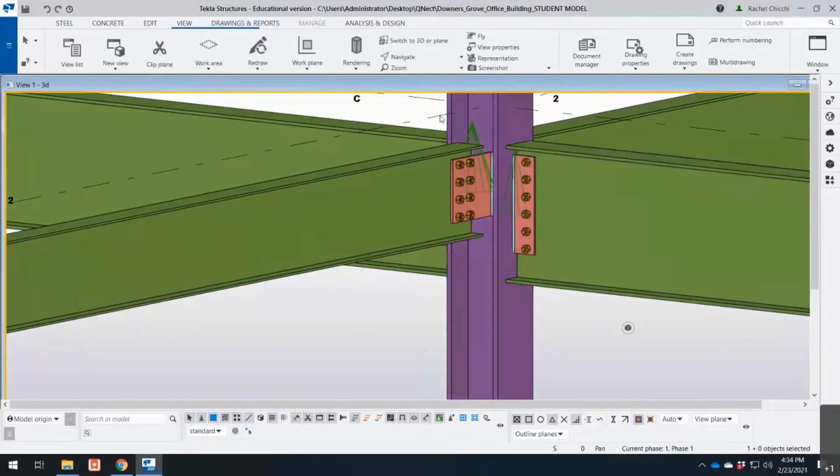So there isn't a top cope on the beam. The top cope was needed in the beam to girder connection because of the girder flanges. Here there aren't any conflicts in the beams, so we would easily be able to lower it into place without needing a cope.